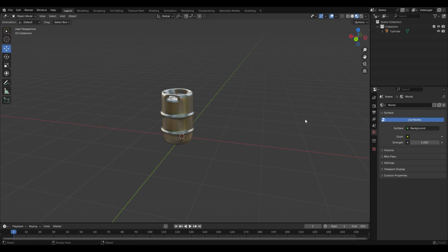And we're going to, let's see, batch mode. Where is it? Embed textures. So we want our texture to go with it. Now we're going to call it beer keg FBX into our file, and we're going to export the FBX.